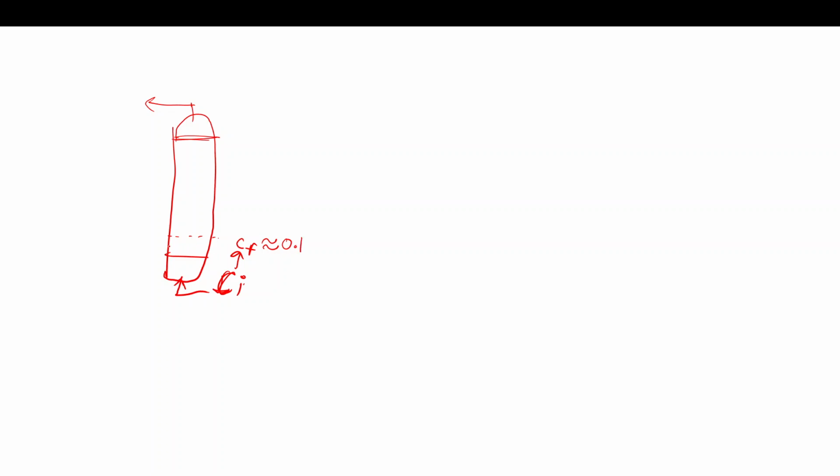So here only there will be adsorption. Firstly, it will adsorb completely. So this is the zone in which it will get completely reacted, and this much portion is completely unreacted or unadsorbed. So this is the unutilized bed, and this is the utilized bed. So here the adsorption occurs like this.